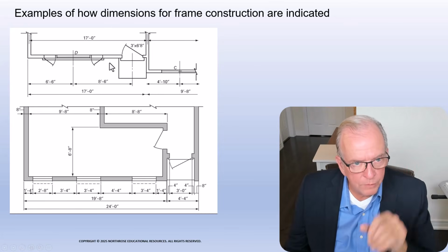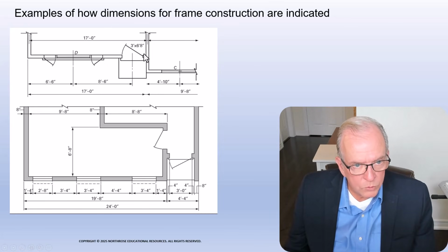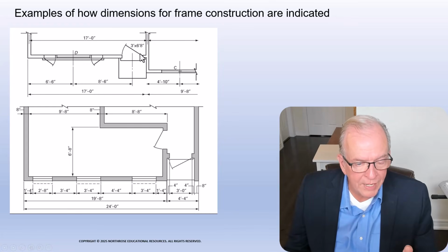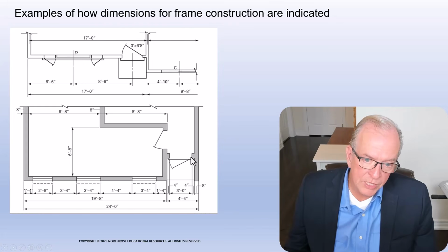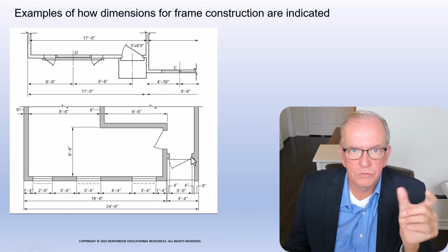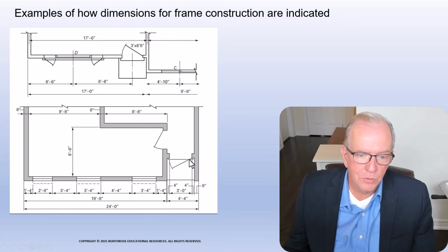This is looking at a plan view of a drawing. This is the swing of the door. So this door would be a right-hand door, because if you stand in the doorway looking this direction, your right arm is on this side. That's how you tell whether it's a right-hand or a left-hand door. If you stand where the hinge is here, I always refer to it because the technical name for a hinge is a butt hinge. All right, so you go in and actually look at the hinges they use for doors. Technically, they're called butt hinges. So I always say you stand with your butt against the butt hinge, looking this direction. Okay, well, if I'm looking that direction, my left arm is here. That's a left-hand door. If I'm here, my butt against the butt, that's a right-hand door. That way you won't make a mistake.